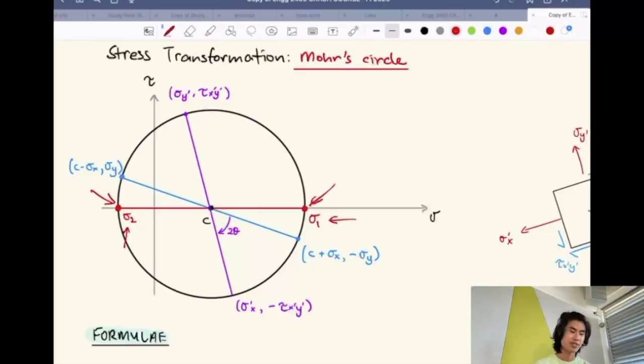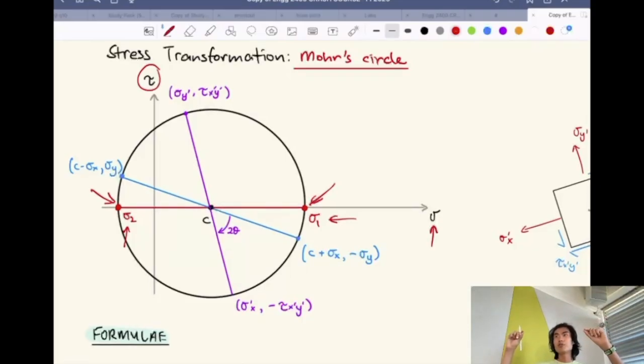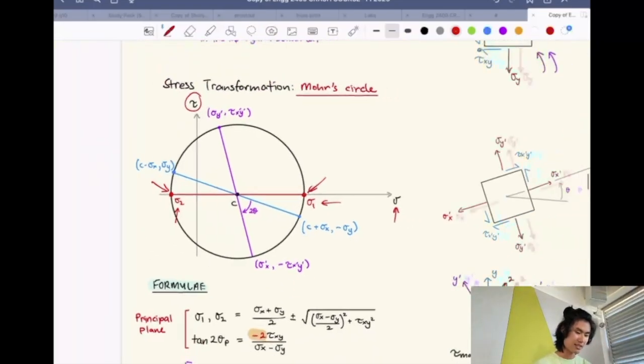Right? So this is your stress values, and then your shear values sit here. What it's kind of saying is that when your shear is at its maximum, your stresses are not at their maximum, and when your stresses are at their maximum, then your stress element isn't going to shear at all, because there's no other force being applied to the stress element in the opposite direction. So it can't shear in any way. And that is the transformation.